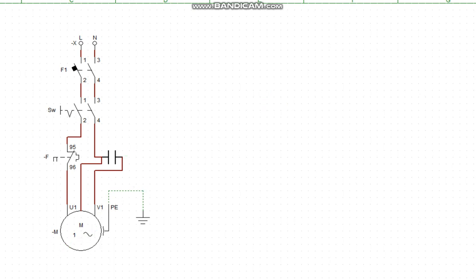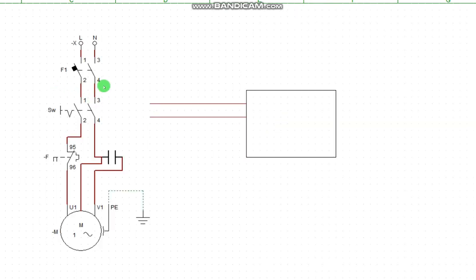Let me, for instance, say this is my flow switch. If I have this as my flow switch and I have a cable, don't do this by taking cable from here and cable from here, and this is your flow switch, and use it to integrate this place by taking away this and putting it here and returning back here. So that flow switch will be closing and opening to determine the current. So in that case, the load will pass through here and go to the flow switch and come out and now power your motor. No, that is a very wrong practice, please.